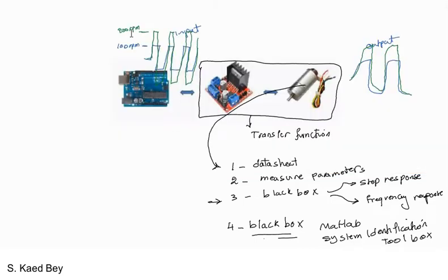It seems at a value of 200 RPM, the motor responded reaching almost the 300 RPM, which is the saturation number. So I will modify this. I'll tune it to 150 RPM instead and repeat the experiment.